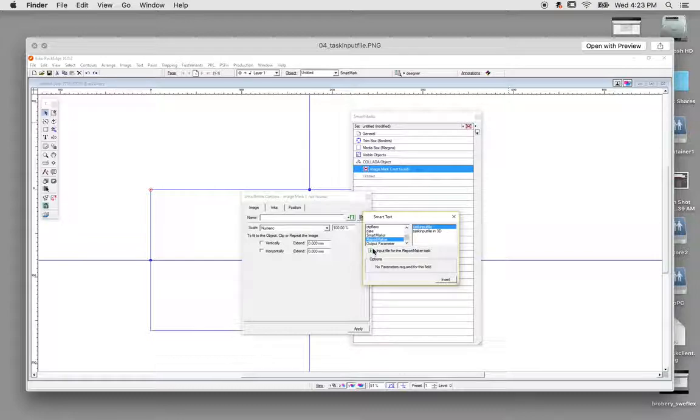Now when you do this, make sure you have a connection to your Automation Engine server. For that, you will have to go to Edit, Preferences, and then you go via the tab menu to Server and Resources, and there you can find your server.